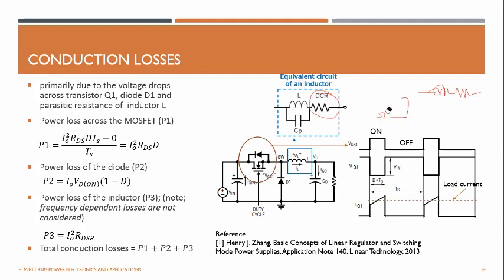Every coil, due to its copper loss, has a resistance. And there are also some capacitances between each and every coil turn, which added together give an equivalent capacitance. If you build a coil like this, there is a parasitic capacitance between these two segments, because in any coil, when the charge is passing, some kind of capacitance occurs.